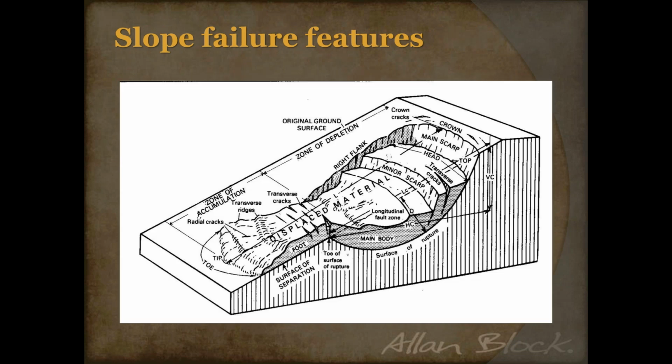All right. First, here's a quick pictorial line art description of a global or slope failure. The slope was originally pretty consistent, but some changing parameter, be it a rainstorm or water event, changed the stability of the soil. Maybe it was a seismic event. Maybe it was deforestation. Maybe somebody dug out the foot of this wall, making the upper area just slide down to come back to equilibrium.